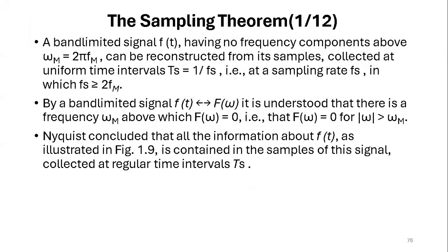Now the sampling theorem. A band-limited signal f(t) having no frequency components above omega_m, or 2 pi f_m, can be reconstructed from its samples collected at uniform time intervals.